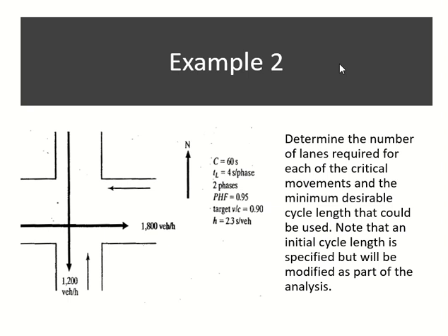So 2 phases, 2 movements. This is how they made it possible. Only one movement is allowed, only one movement is happening from each road. You cannot even see a left turn here. Many of the movements are blocked. That's why two phases can work here, because you are only dealing with two movements. So you can reduce the number of phases, but that also means the number of movements should be less. Otherwise, it will become very difficult, or even unsafe as well.